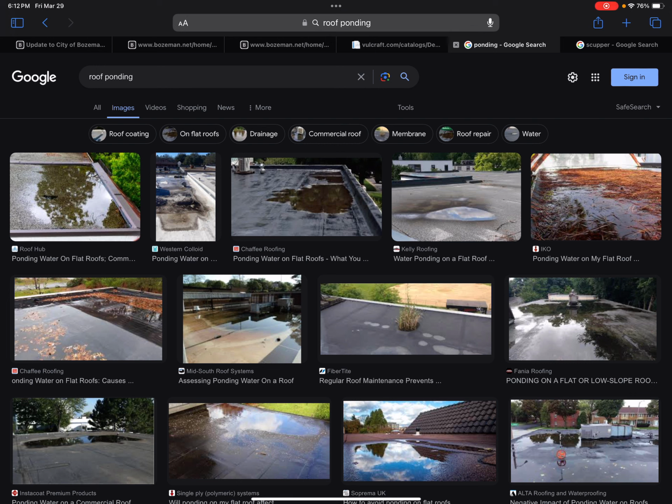And not just water that builds up on roof due to rain loads, but on top of that, we have to worry about once the rain loads hit the roof, then it makes the roof deflect. Then it takes more rainwater to flow out through the drains and whatnot. And so we're really worried about that additional water on top of the rain loads.